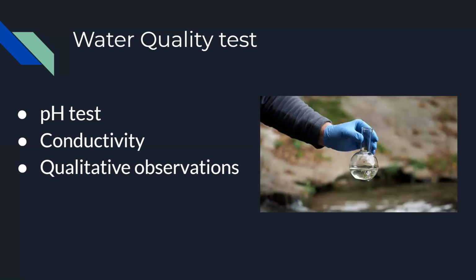Then the sense of taste can detect concentrations of a few tens to several hundred ppm, parts per million. And taste can indicate that contaminants are present, but cannot identify specific contaminants. Then the color may suggest that organic impurities are present. In some cases, the color of the water can even be caused by metal ions. Color is measured by comparing different samples visually or with a spectrometer. This is a device that measures the transmission of light in a substance to calculate concentrations of certain pollutants. When the water has an unusual color, this is generally not a health concern.